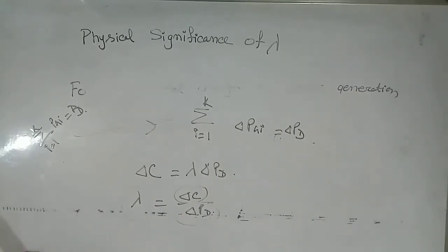As incremental cost is increased or decreased in the iterative process, if a particular generator loading PGj reaches the limit PJ min or PJ max, its loading from then on is held fixed at this value, and the balance load is shared between the remaining generators on equal incremental cost basis.